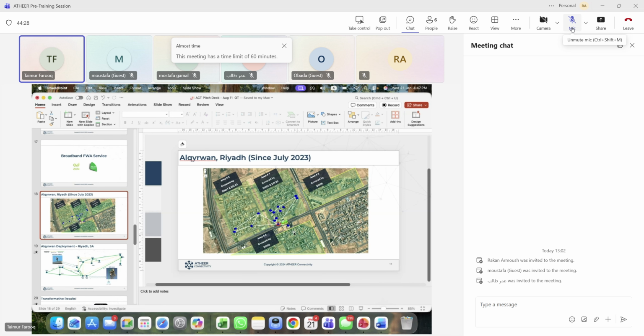Just like this. You set up one building, and from the building, you start connecting the sites that you have line of sight to. And line of sight doesn't mean that it has to be a 40, 50, 60 meter tower. For example, if you have a radio on one of the 2 or 4 story buildings and the other offices or buildings around it are 3 or 4 story, then definitely you have line of sight. It's just beyond those buildings you will have issues, and you can actually use those buildings as a repeater.